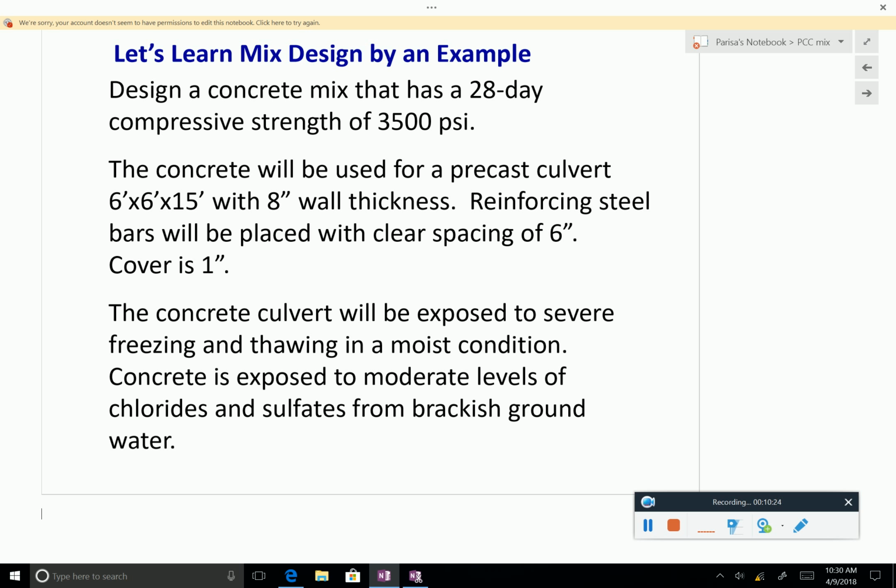Very briefly, I've talked to you about this last time. How long does concrete take to develop most of its strength? Remember I showed you a graph and you could see day 3, day 7, day 14, day 28. And I told you that concrete gains strength with time. So as you cure it, it becomes stronger. And we assume that by 28 days, most concrete types have achieved around 85% of their strength. So that's where the 28 days comes from. You hear this all the time.